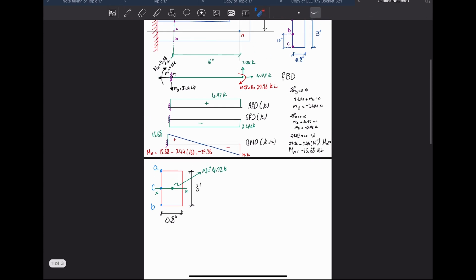For the shear force in the cross section itself, it's not going to matter. I know that it's vertical shear, so if anyone puts it up or down, it doesn't matter as long as the shear is vertical. But the direction will matter later when we talk about the stress element. So let's fill this in: V is equal to 3.44 kip. At this section, I do have 3.44.